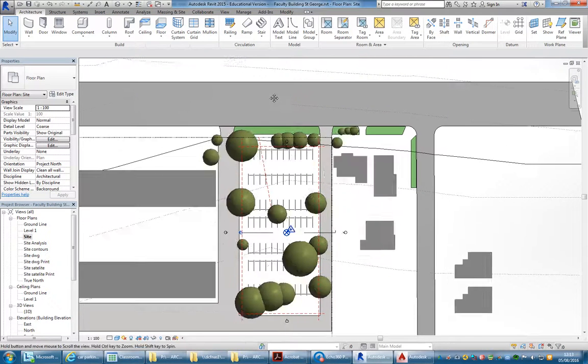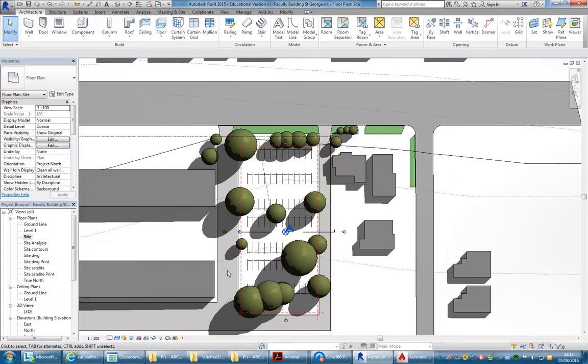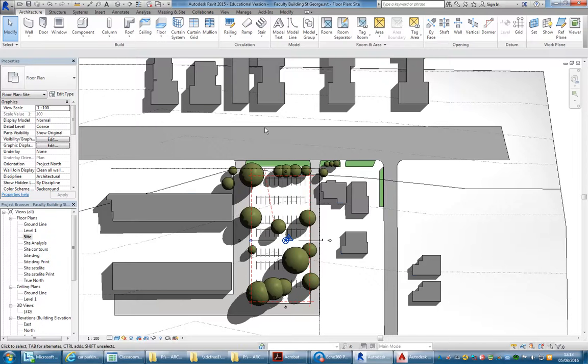And then later, once you have an idea of your grid layout, you could put some grid lines in, probably following those reference planes, but then also in between that as well. So again, you're trying to set out your horizontal dimensions in plan. And then in section, you need to set out your heights.